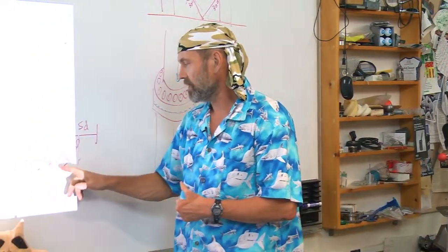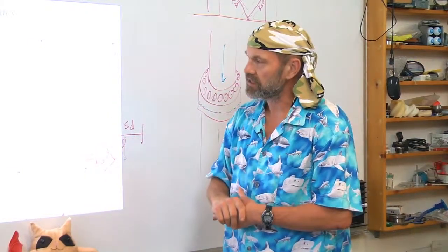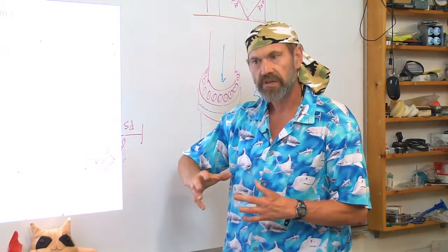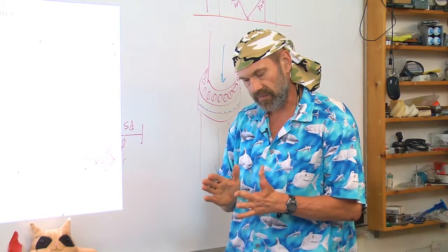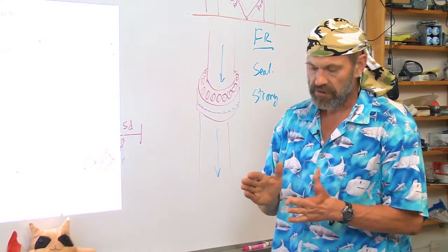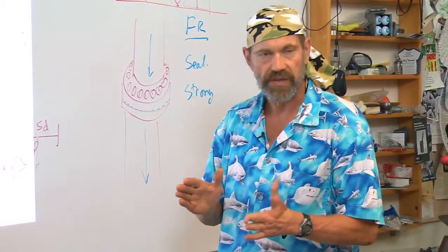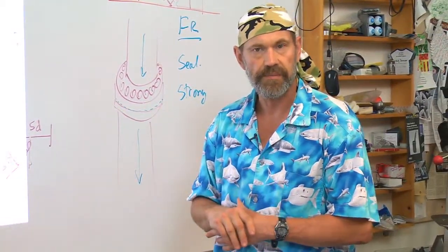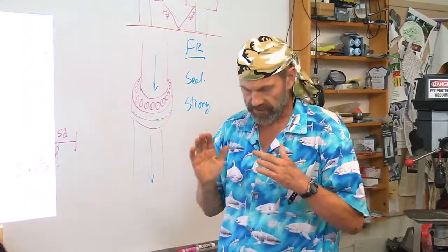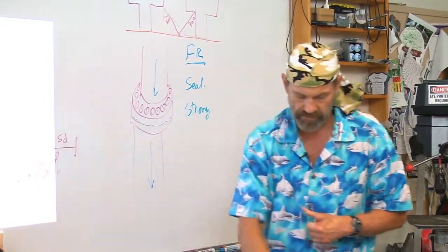And furthermore, when I design my bolted joint in the context of looking at the springs, I can figure out how tight I have to tighten the bolt such that when the interior pressures or forces acting on the joint happen, the alternating stress seen by the bolt is low enough that I will not fatigue that bolt with time. All this is covered in the text. Make sure you're familiar with how you do that calculation. Very critical.